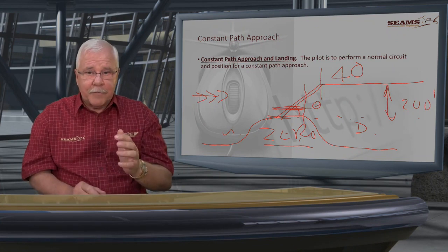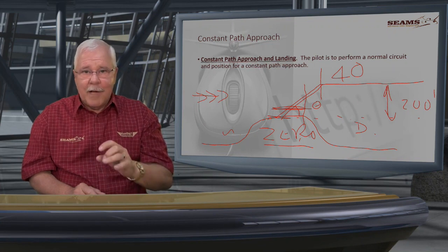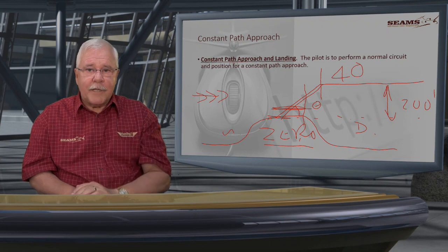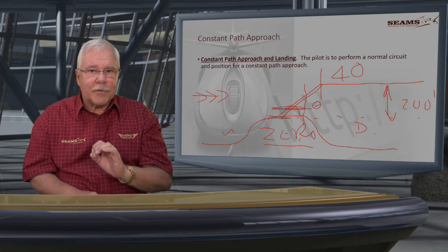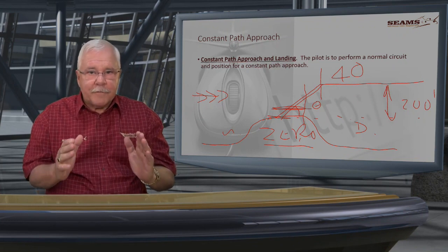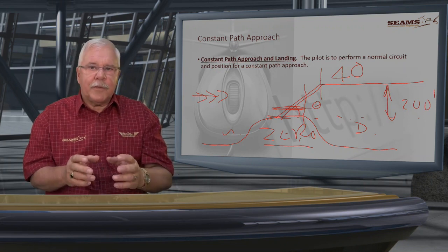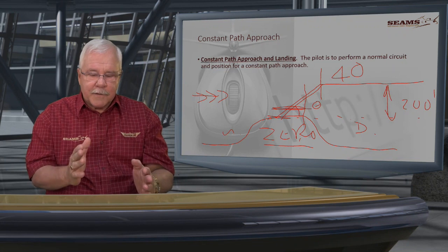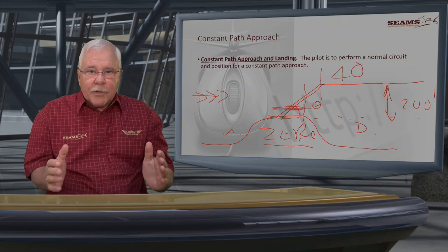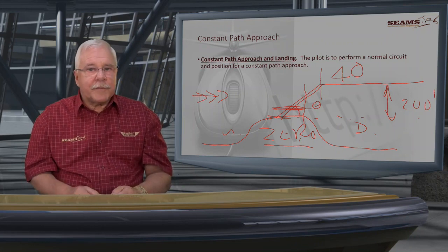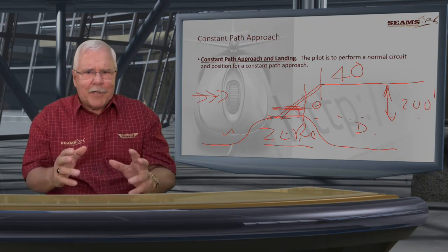Stick to those rules and you can fly into a stadium, confined area landings, mountain tops, any and all NVG approaches. And you will not pick up vortex ring state, or even come close to that, in the transition phase. Let's now, just for this argument, and don't be too puristic on me, below 20 knots down to 0 knots, you can have a rate of descent of 350 to 500 feet a minute. Remember, we were taught vertical descent at 500 feet a minute. So get over that one.